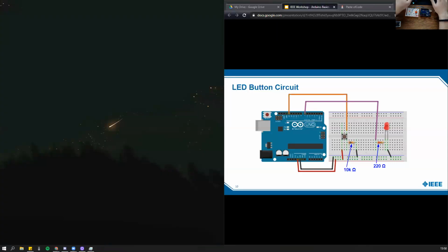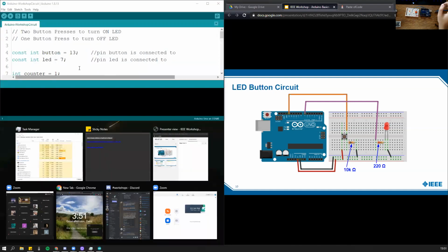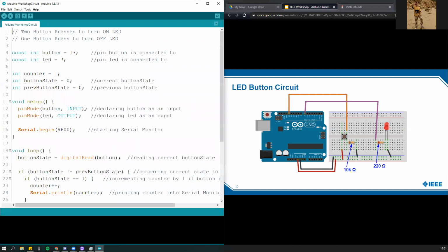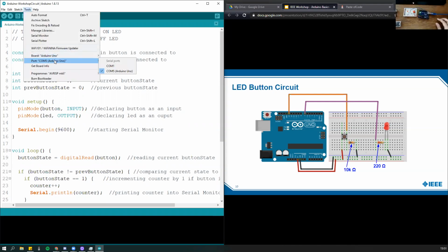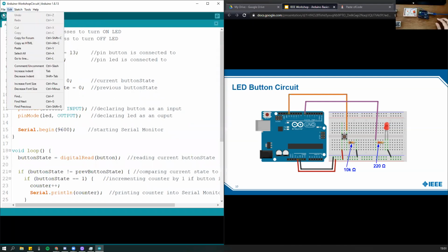So when you first open up Arduino, it has the loading screen, and then it loads the most recent save. Okay, so let's go back. Let me plug this in. Okay, and then just make sure the board and Arduino port are correct. Then we can go into verify.